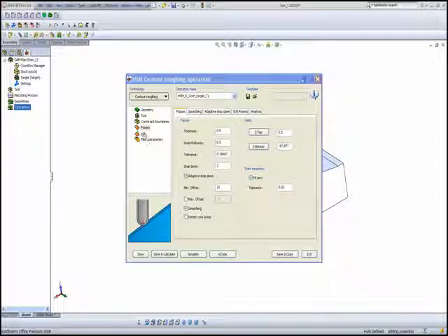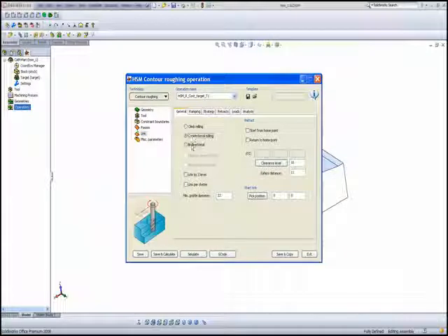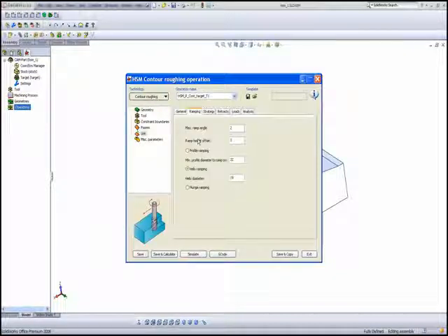If we continue on now to our links, we have the choices of working climb milling or conventional milling or in bidirectional. I'll be choosing to use here to work in climb milling. Now if I go into my ramping area, you'll note that we have different ways of ramping into our part, whether it be profile ramping, helix ramping, or plunging ramping. I'll use the helix ramping.